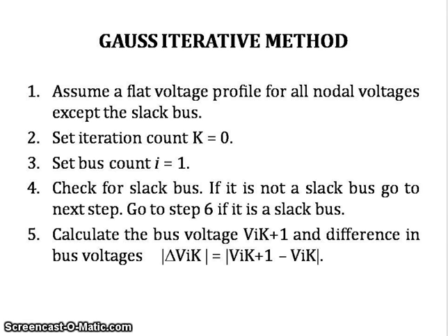There are basically three methods to arrive at the solution of the load flow problem. As we discussed earlier, the load flow problem is to compute all the parameters, that is active power, reactive power, voltage, and power angle delta for all buses.